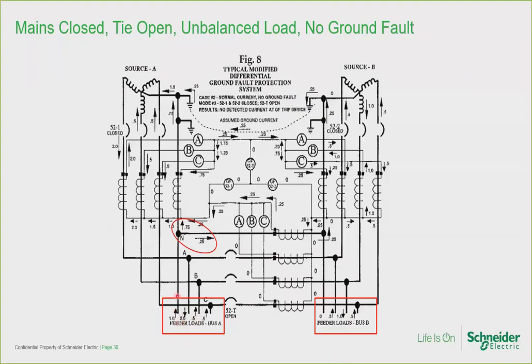Our analysis will show that none of the main circuit breakers trip on ground fault because there is no ground fault, only unbalanced load current. I showed you earlier that in the absence of a ground fault scheme, by just putting LSIG trip units on the main breakers, an unbalanced load could cause nuisance tripping of the breakers. They could nuisance trip as though a ground fault were present. Please draw your attention again to the 3 Y-connected ground fault relays in the upper center of the drawing.